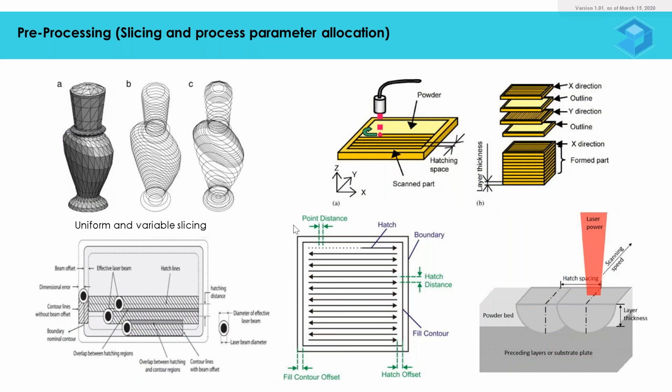So another watch out for 3D printed component is how smooth the surface finish can be. That is dictated mostly by the slicing. So at which layer thickness you are going to process, that choice is very important. As well as over here you can see typical infill for ensuring good dense parts.